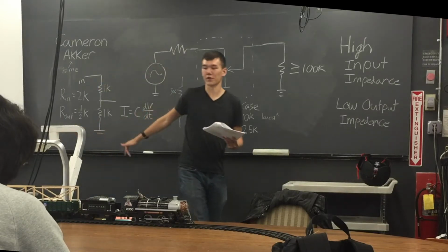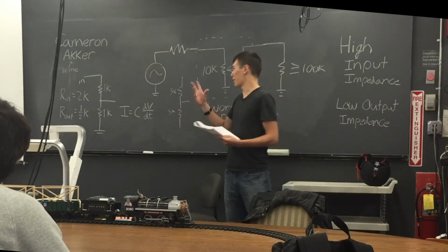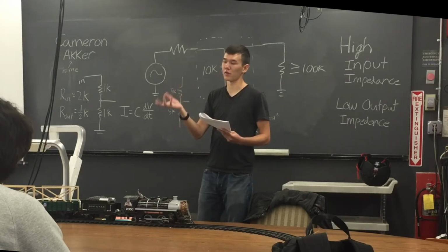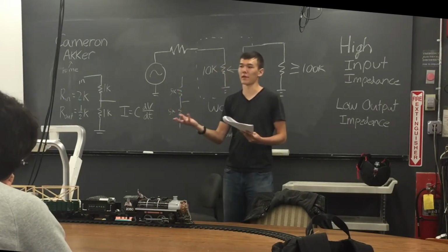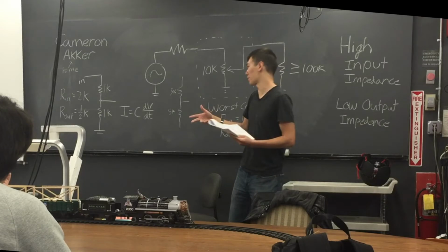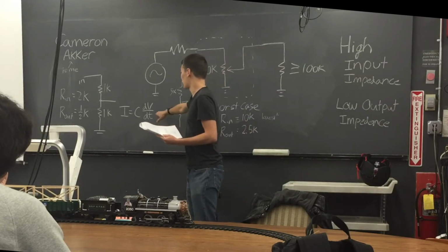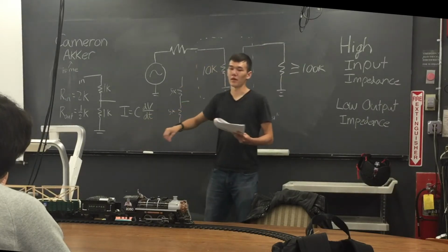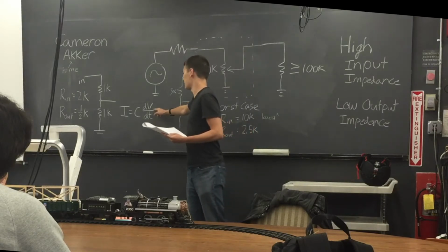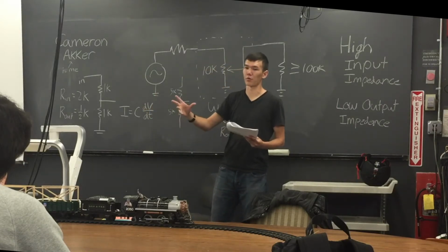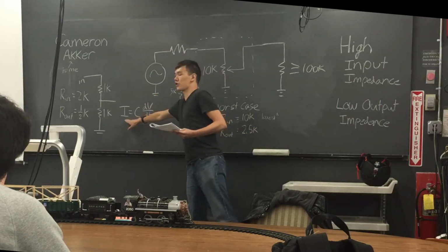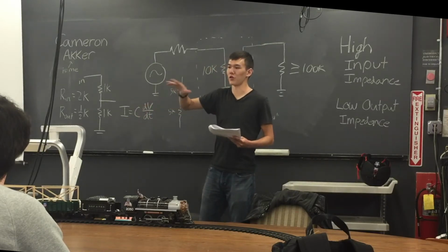The I is the current on the other side of the capacitor, and what that current essentially does is start to fill the capacitor. It's adding electrons to the capacitor, increasing the voltage on the capacitor. That's dependent on the change, the dV/dt. The thing is, this dV/dt value is also swinging back and forth with your input signal, and it's the current that's changing. Nowhere in here does it say voltage on the capacitor.